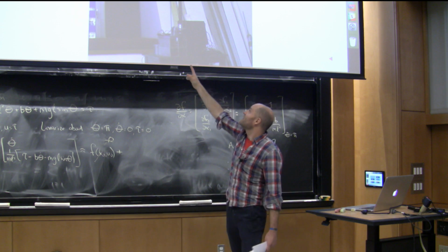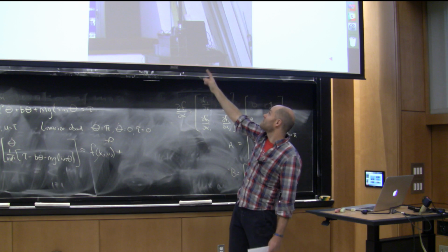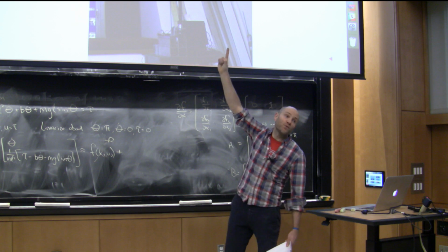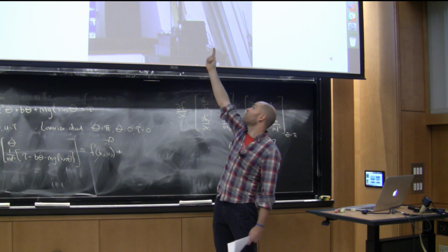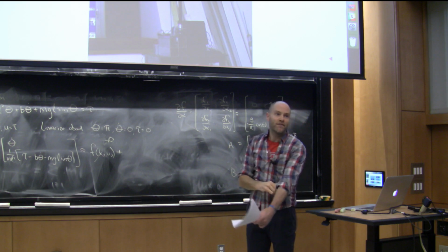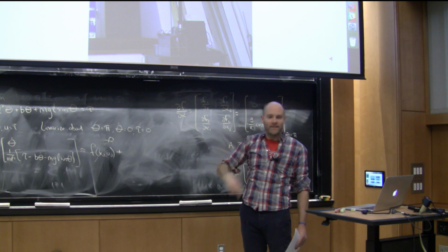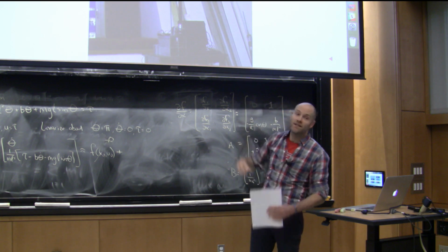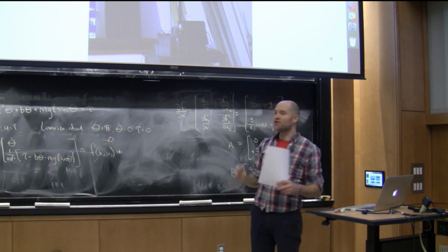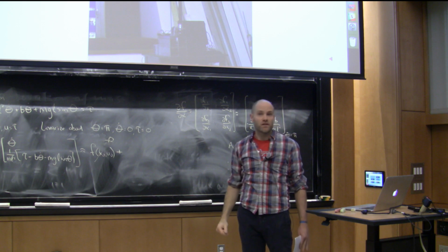Now the problem is you've already got a lot of things hanging off the first link, so it's easy to make the first link heavy. Because the motor, for instance, wants to be at the elbow, we actually put the motor at the shoulder and have a drive shaft going through to try to minimize the distal mass, and put the inertia of the first link as close to the base as we could. Okay, but still, that first link tends to have more stuff on it and gets heavier. The second link can just be a hollow tube, but then you get that effect. So you've got to put a slug on the end of it, right? Some mass at the end. The property you seek is called strong inertial coupling, where you have enough inertia in the second link to change the coordinates in the first link.